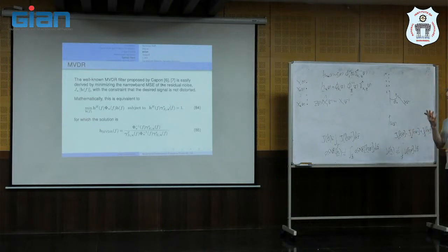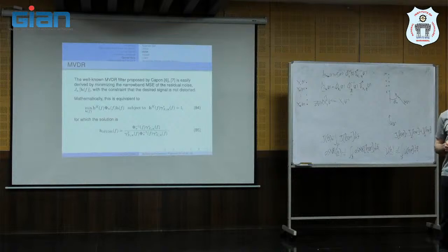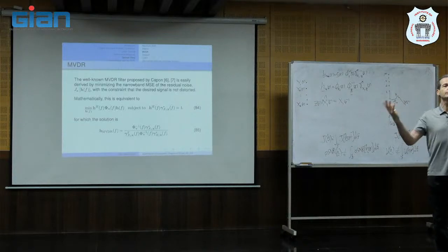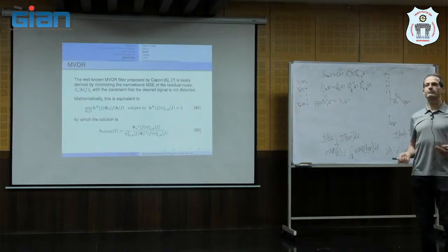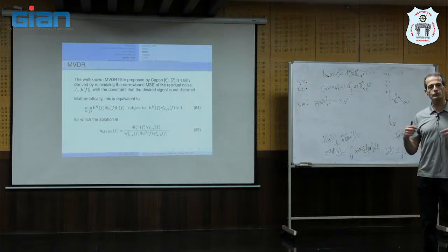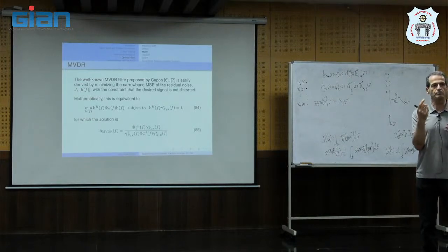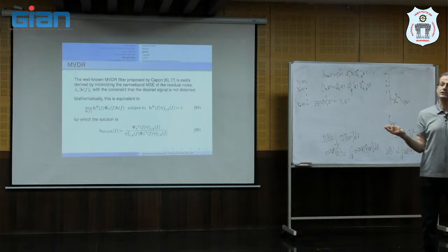So if I want to minimize the broadband distortion, if I don't have 0 distortion in each frequency, but I want to minimize the distortion by some filter, and I want to minimize the broadband, because usually in applications we are interested in the broadband measure. So I need to make more effort to minimize the distortion in the more significant components, where the desired signal is larger.